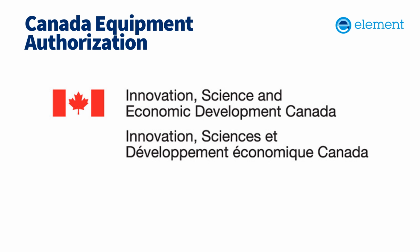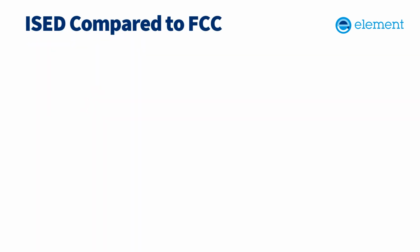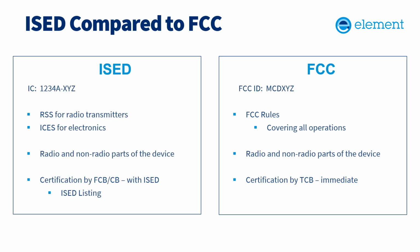For Canada, as I say, Canada is just a little bit different. So I said, in terms of labelling and comparing it to FCC, you'll see at the top we have an IC and an FCC ID. So these are physical certification identifiers that have to be applied to the physical product itself. And then for Canada, we use RSS standards for testing of radio transmitters and ICES standards for testing of non-intentional radiators typically.